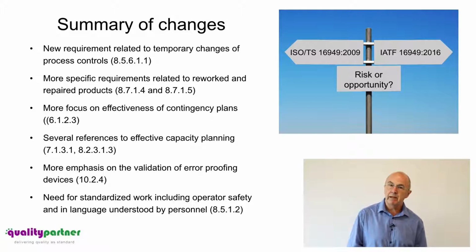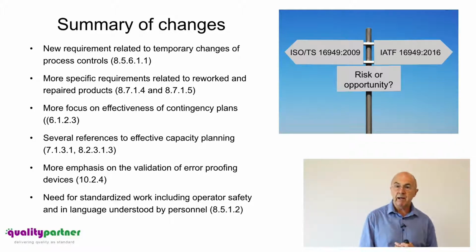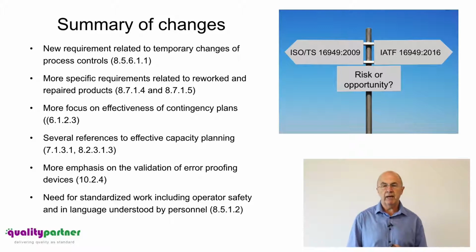This may be due to unavailability of maybe some measuring equipment, breakdown of some measuring equipment, unavailability of a key production process. How are we going to manage that change? Thinking about the risk within that through the FMEA, thinking about the controls within the control plan, and thinking about the standardised work as to how we communicate that temporary change to the employees working within the process.